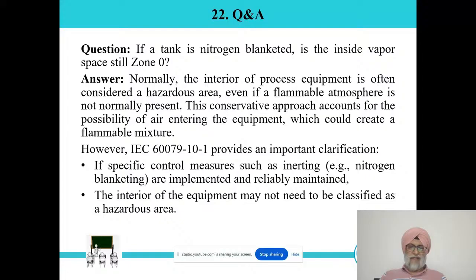Normally, the interior of the process equipment is often considered a hazardous area even if the flammable atmosphere is not normally present. This conservative approach accounts for the probability of air entering the equipment, which could create a flammable mixture. So there is one option. Qualitatively, of course, for the safer side, we should consider it because we do not know the concentration of flammable mixture inside, and that depends upon the pressure also, and the concentration of oxygen.